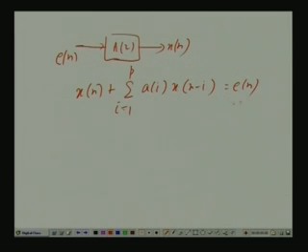If it is an AR modeling problem, e(n) is a white sequence and is orthogonal to all the past of x. In the case of linear prediction, e(n) is not a white sequence. e(n) is orthogonal only to x(n-1) up to x(n-p). In general, it is not an orthogonal sequence. In any case, e(n) will be a sequence, so you can model this even in the case of linear prediction.